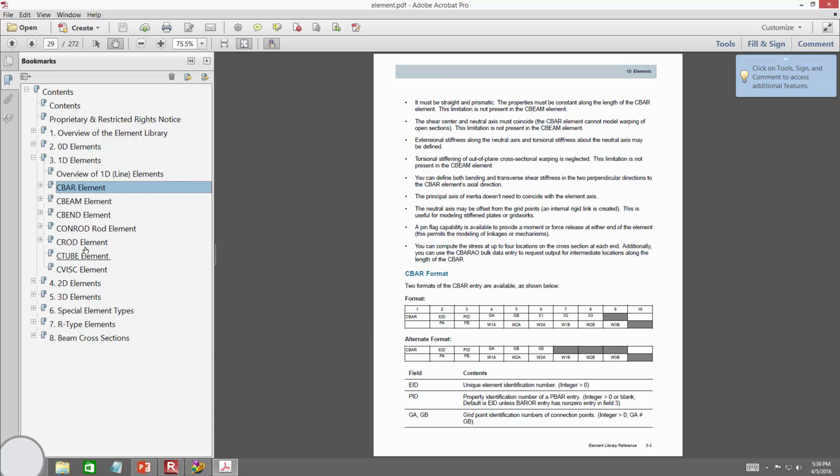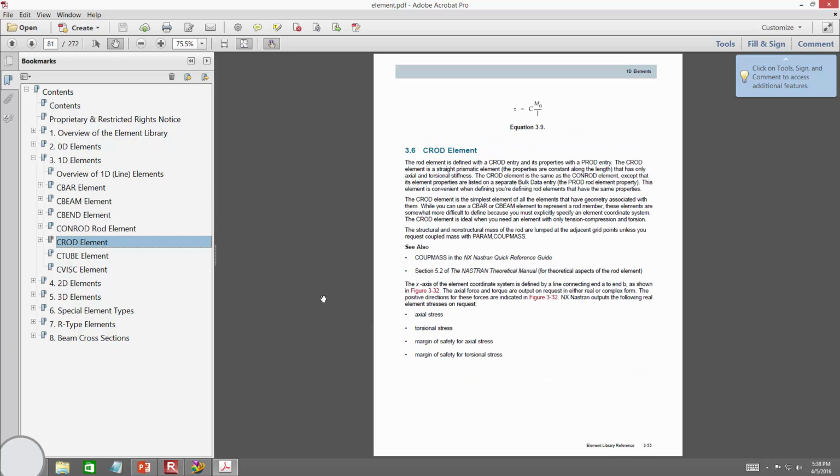Now, if you do a little bit of research and actually look at the rod element, the rod element is probably the one that makes the most sense, because the only thing that rods do in NX-Nastran is stretch and twist. That's it. If I took a C-rod element in NX-Nastran and tried to bend it, the program would shut down and say that it doesn't understand, okay? Whereas all we're doing to these elements is stretching them. We're not even twisting it, but it can handle that.